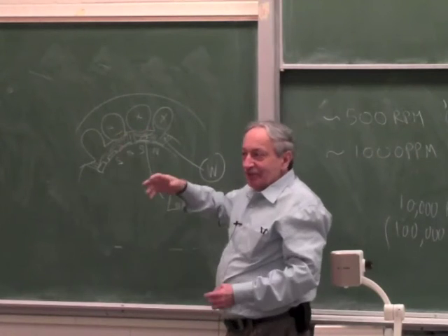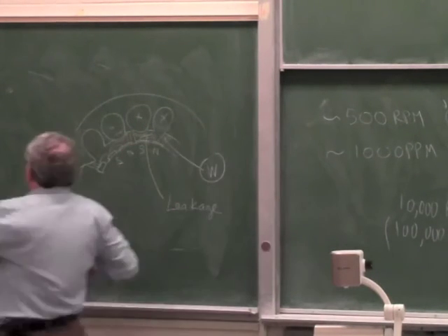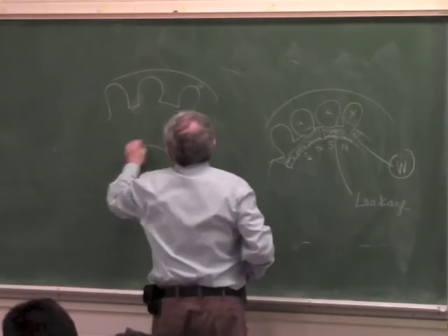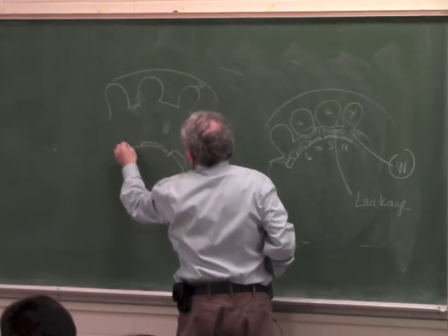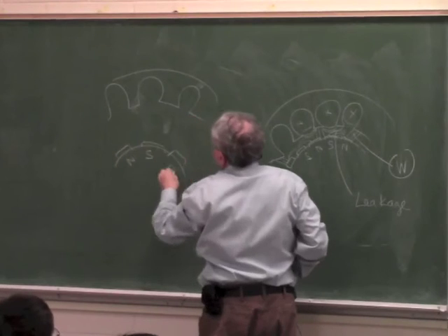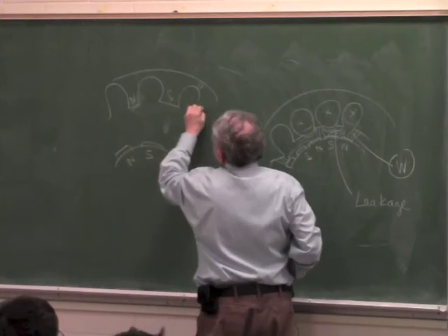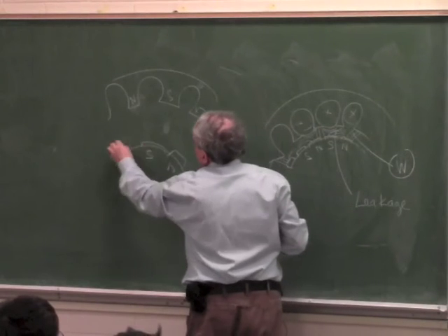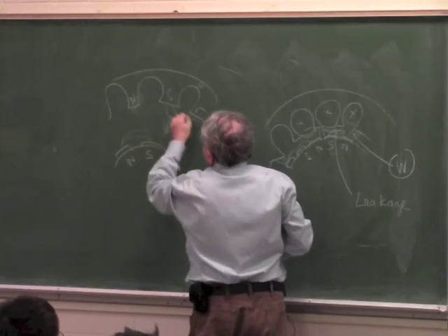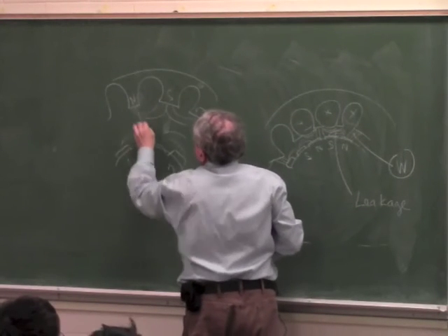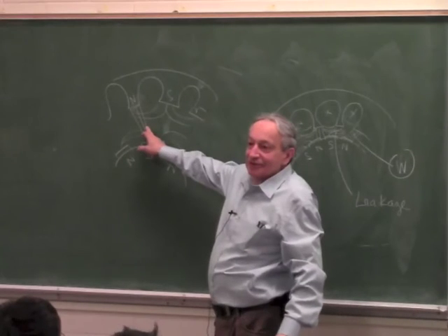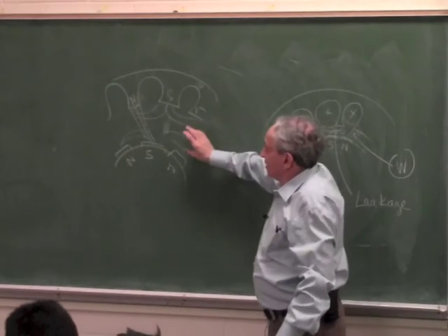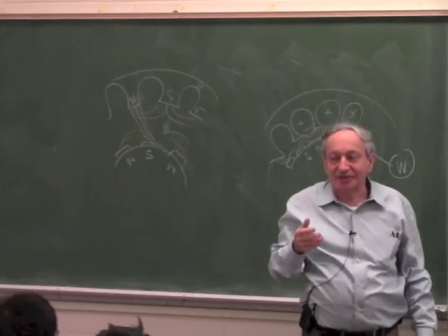So basically you can see, just to exaggerate, if you made a motor which looked like this and had a huge air gap, this is NSN, and this is again NSN. If the air gap is huge, it's easy to see the motor will have very terrible efficiency, because most of the flux will short and very little of the flux will go to where it produces torque. Is that clear? So in a real motor, you're trying to make this air gap as small as possible to increase efficiency. But if yes?